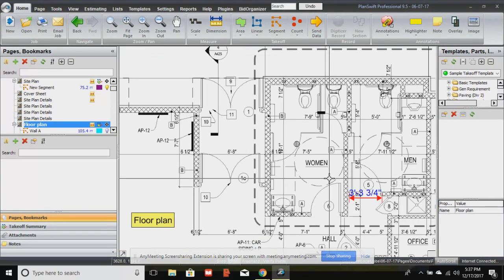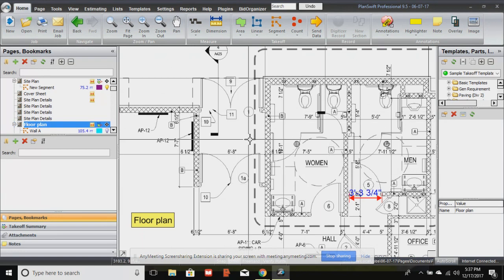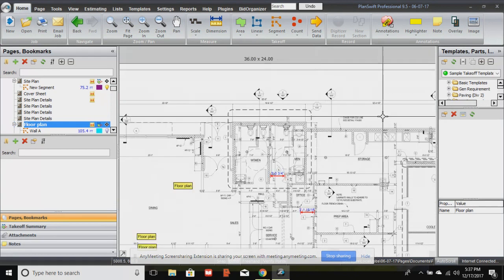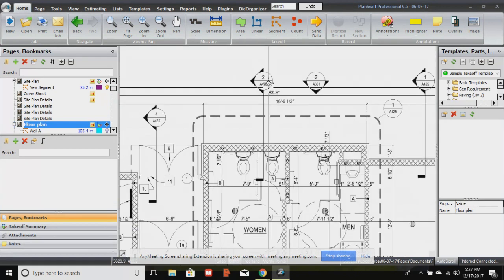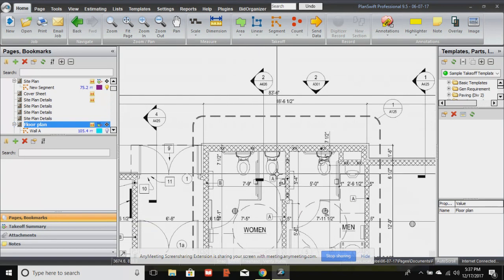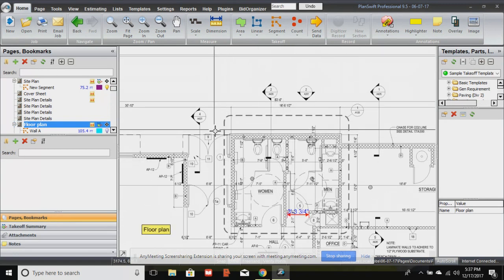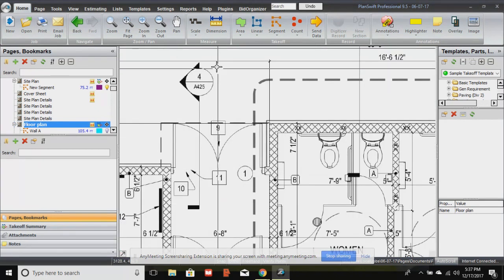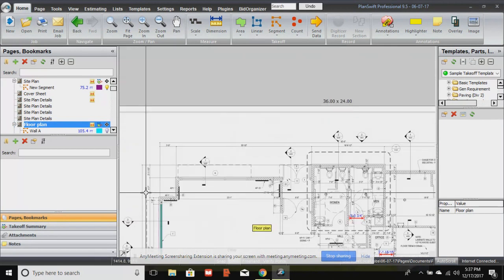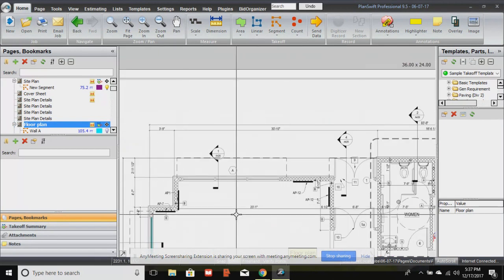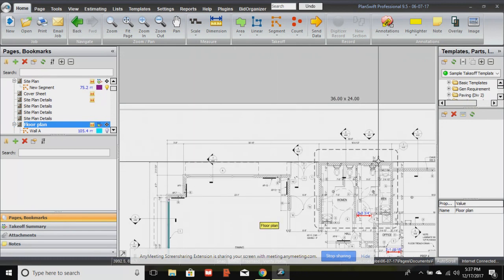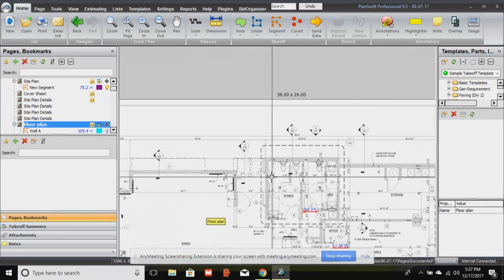And so everything here has a meaning because the architect needs us to build these walls in the correct way. And so all throughout the project, the architect is saying, by giving you section view markers, Carpenter, here at the exterior bathroom walls, I need you to understand that wall construction is that way. Here at the double doors, that wall construction is that way. Okay? And so it's just at those individual points in time. That's why you have so many of them. Over this window, at that door, at the rear of that bathroom, here at this stretch.